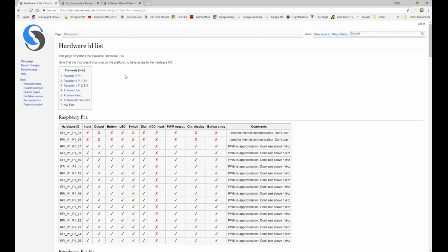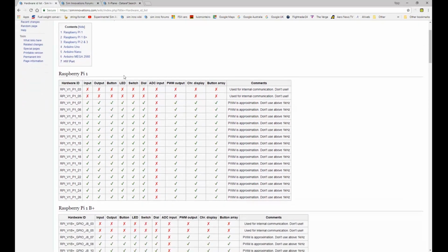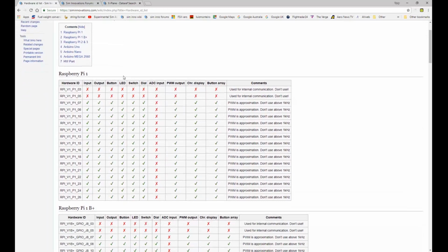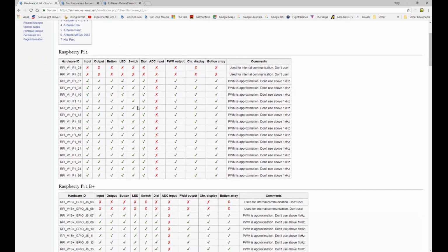Whether that be a Raspberry Pi, you could plug it into the USB of the Raspberry Pi, or just another Windows machine that's running Air Player. The particular hardware needs to be plugged into that machine. So that's an important note, as a few people have come a cropper with that: the hardware not being recognized and not actually functioning, even though the code is perfectly okay.